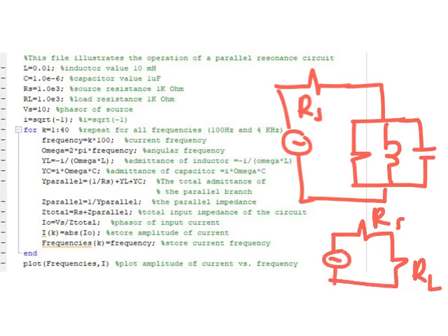At any other frequency, the RS and RL will try to dampen; their combination will be in parallel with RL, and as a result, the net impedance will be weaker. Then the output voltage that you can measure between these two terminals will be weaker. So only at resonance are you going to get this behavior here.